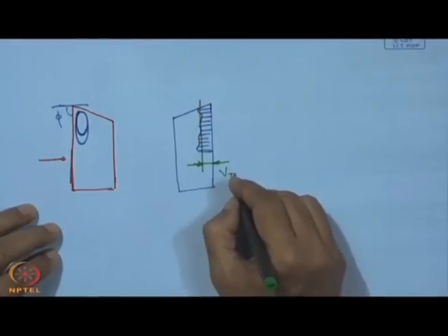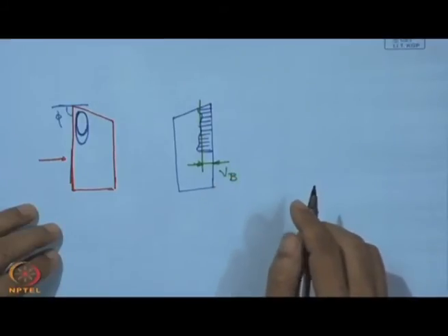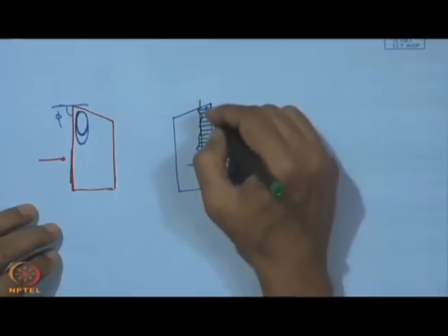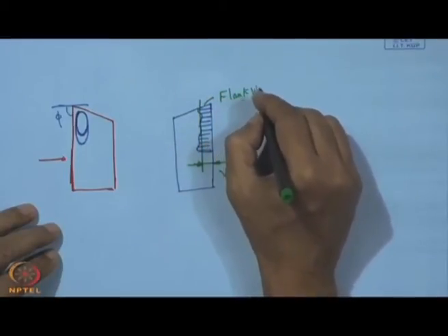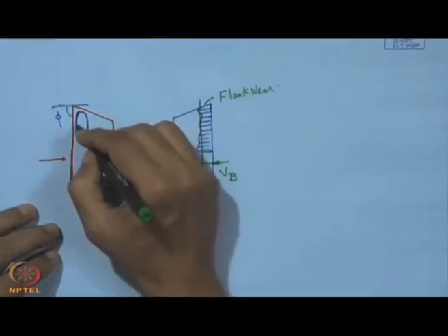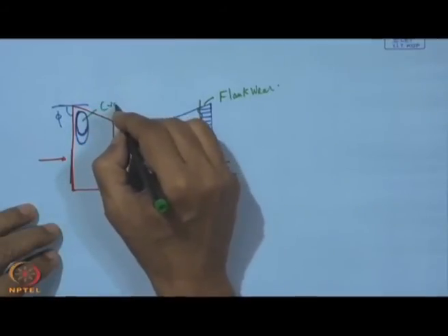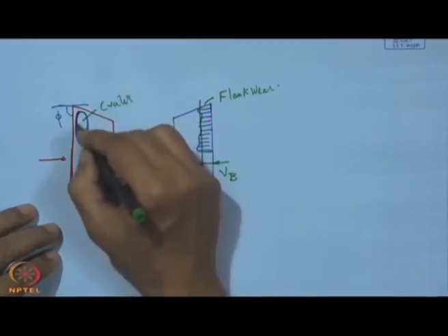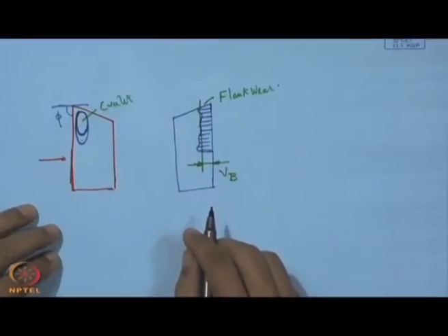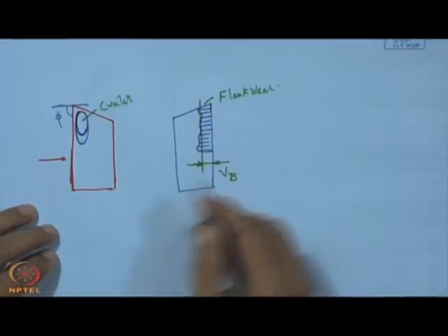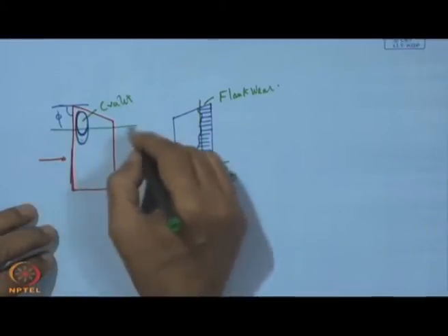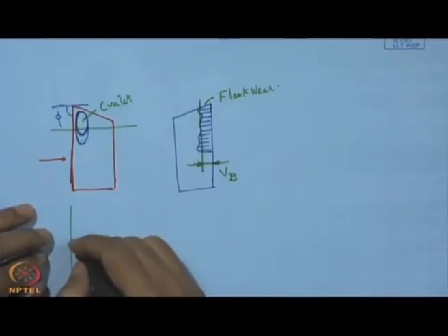Okay. Average value, that is called the average flank wear. So, this is actually the flank wear, and this is called the crater wear. So, this is a cavity formed on the face of the tool, and this is the flattening of the wear, and this one, if we take a section to this here, what we find is going to be a face with such thing.